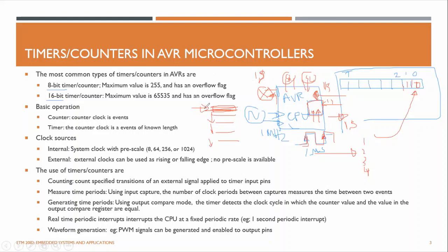Again, it's like an interrupt. So you are working in the main function. When the timer wakes up the CPU, it will go to an interrupt service routine, a different function, do some work and return back to where it was, not being busy in a delay function. So that is one advantage of using timers. And sometimes you can use timers to measure the time between some events. You can count the time, and so that's the advantage of using timers.